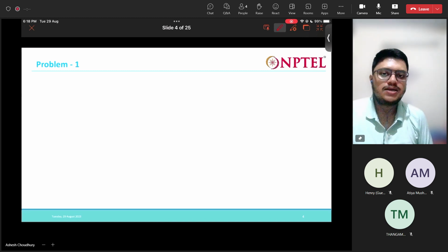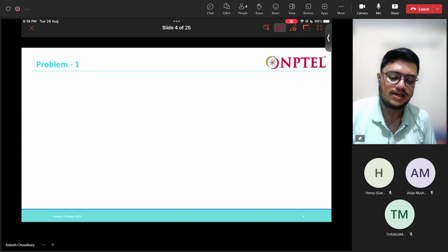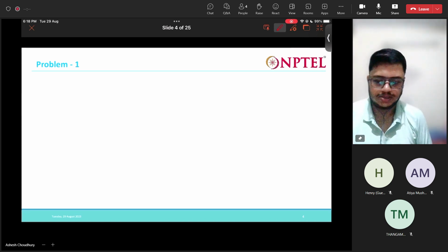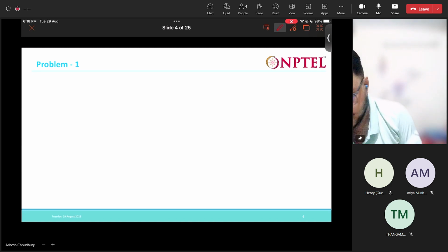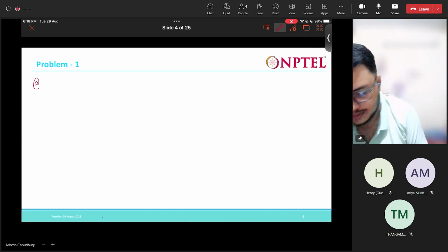The vertical pressure times the earth pressure coefficient will give us the horizontal pressure. We will be writing that expression in terms of Z, the height, downwards. So first, what will we be doing?